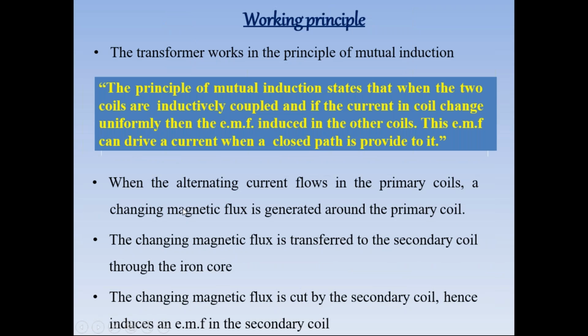Right. Now let us see the working principle. The transformer works on the principle of mutual induction. I already told you that the principle of mutual induction states that when two coils are inductively coupled, here inductively coupled means these two coils are connected through the flux, that's why we call it inductively coupled, and if the current in one coil changes uniformly, then an EMF is induced in the other coil. This EMF can drive a current when a closed path is provided to it. So this is the working principle of the transformer.